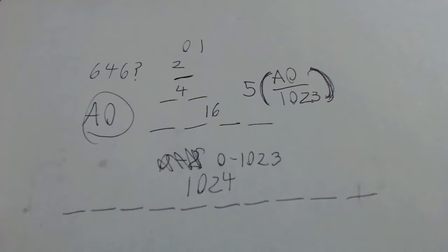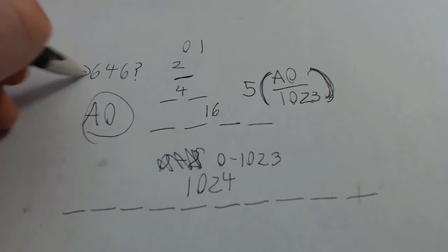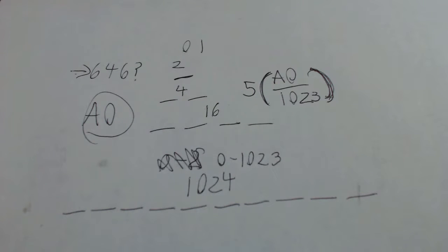That should give us the actual voltage reading rather than just some strange number between 0 and 1023. It's pretty tempting to just plug this into a calculator, but I'm going to do one better. I'm going to program this into our Arduino code and get the Arduino Uno to read us the actual voltage back. Let's give that a shot.